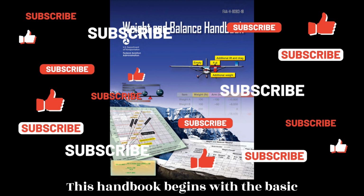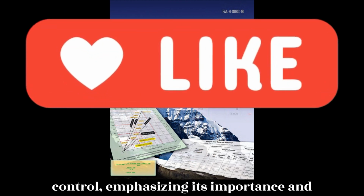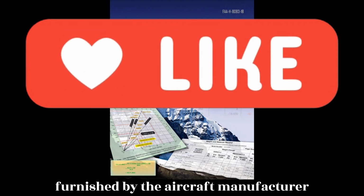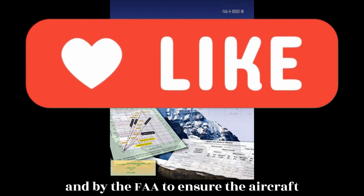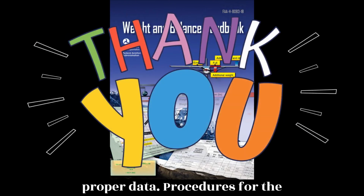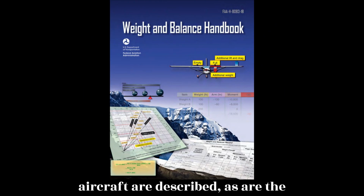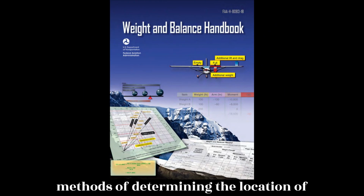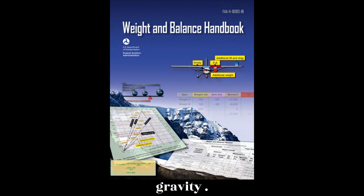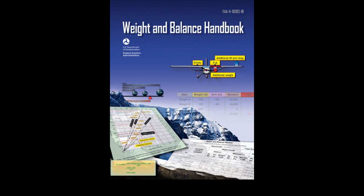This handbook begins with the basic principle of aircraft weight and balance control, emphasizing its importance and including examples of documentation furnished by the aircraft manufacturer and by the FAA to ensure the aircraft weight and balance records contain the proper data. Procedures for the preparation and the actual weighing of an aircraft are described, as are the methods of determining the location of the empty weight center of gravity, EWCG, relative to both the datum and the mean aerodynamic chord, MAC.